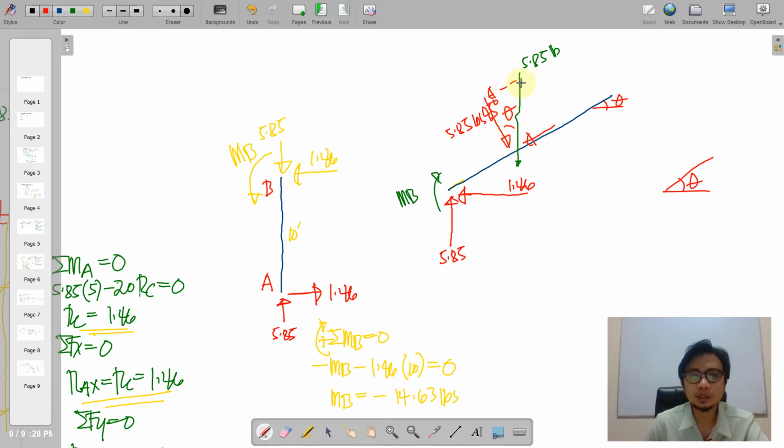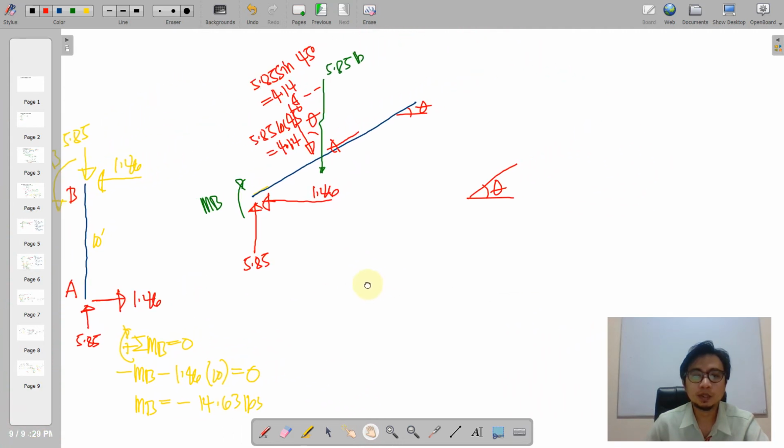If you wanted to transfer this force to include it on the right triangle where it involves theta here, no problem. So just transfer that to that. This is a parallel member, and then we can clearly see that this is opposite your angle theta, and that is basically 5.85 sine of 45 degrees. So anyway, if we have a 45 degrees angle, the value of sine and cosine are just equal. Okay, so we have an equal value for this. We have 4.14, and that is also equal to 4.14. So we have just resolved these components.